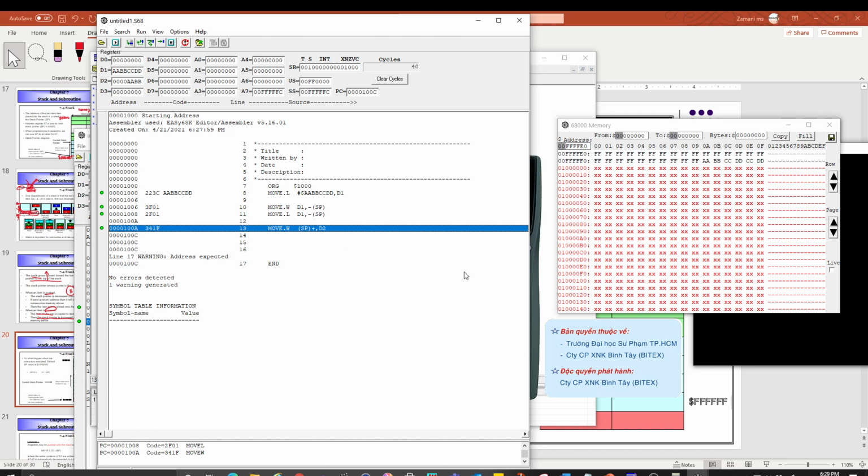Okay, so that's the process of push and pop. You have to remember that every time you push data, the stack pointer will be pointing to a new location. Accordingly, if you push, it will decrease the value, and if you pop, it will increase the value of the pointer based on the size. Remember that W and byte are the same size, minus or plus 2. For long word, it's going to be plus or minus 4. This is a push, this is a pop.